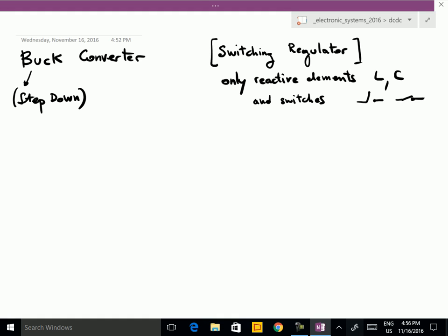And now we see how it is implemented for reducing the voltage, increasing the voltage, changing the sign, and so on. Of course, this is just the ideal situation, because in practice you have dissipation in the capacitances, a bit of dissipation in the switches, and so on.